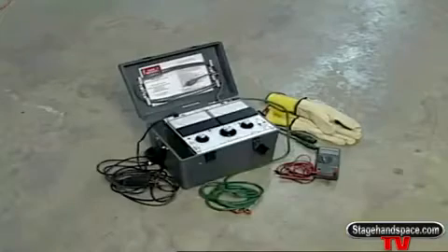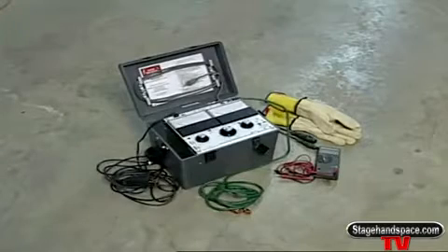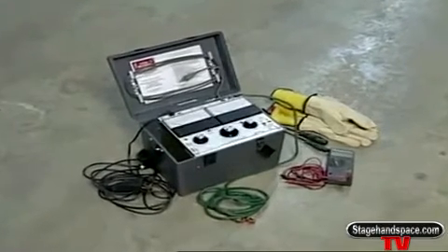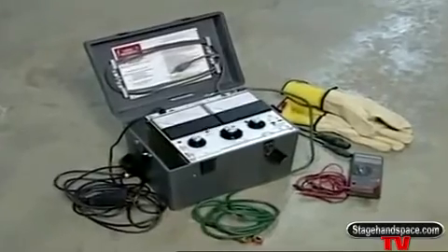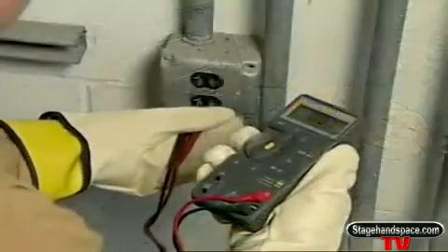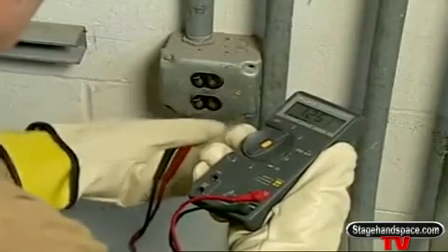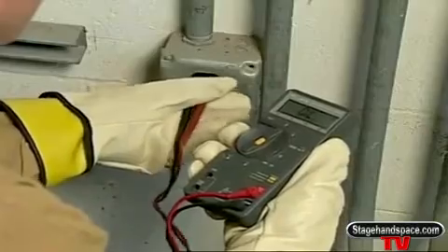Another important aspect associated with electrical safety-related work practices deals with the use of specific safety-related equipment. Test instruments and equipment fall into this category. Only qualified personnel should perform testing work on or near live parts operating at 50 volts or more.